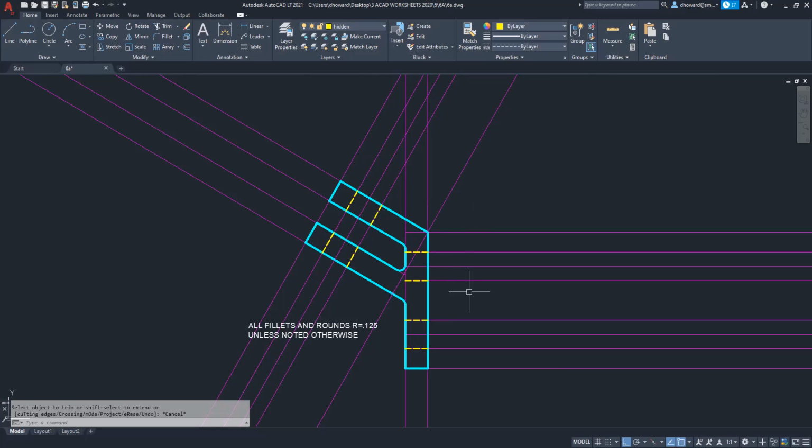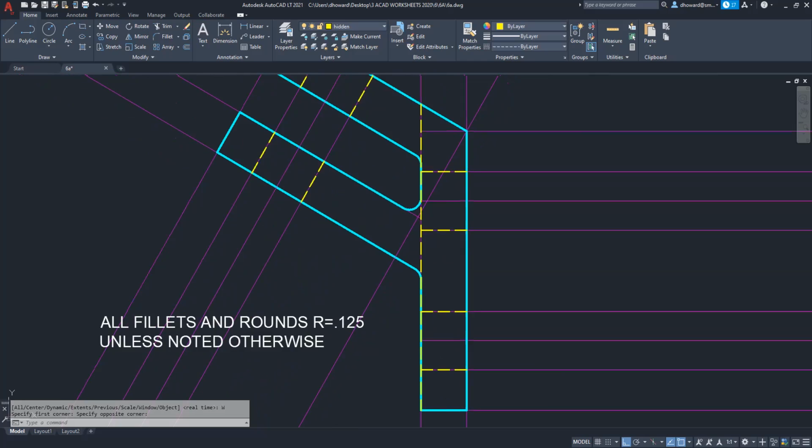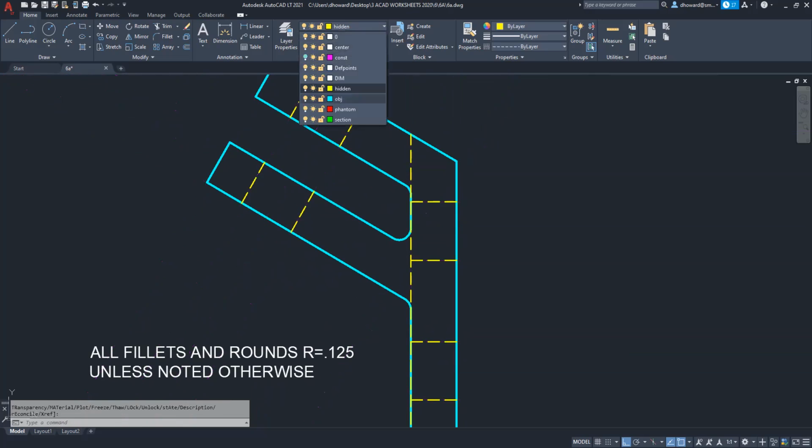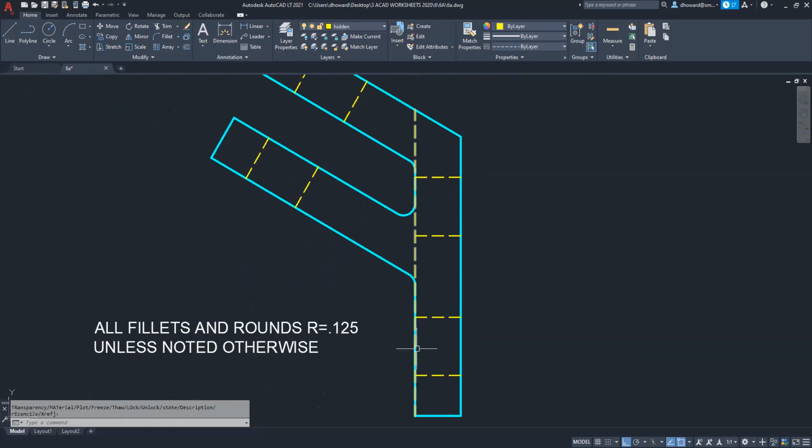So if you were to flip this around and look at it from the other way, these angled faces, these like fingers, wouldn't be touching that edge. So there is a full-on edge on the other side that goes all the way to the top. There it is, that entire edge. Now, of course, we only have the hidden line parts where there aren't object lines. So you would trim that away. You wouldn't have it down here on the bottom. But hopefully you understand what I'm saying, that there is an edge going all the way across on the other side of this, and we need to mark it.